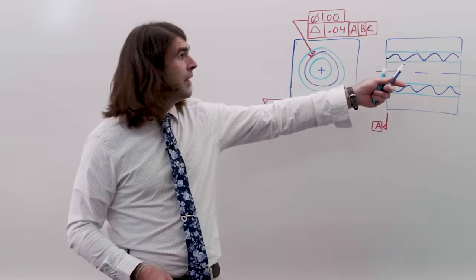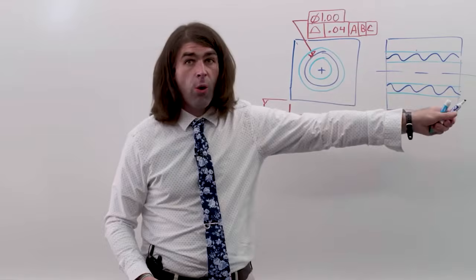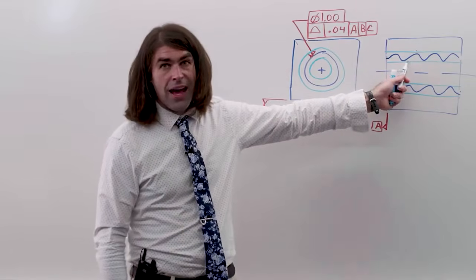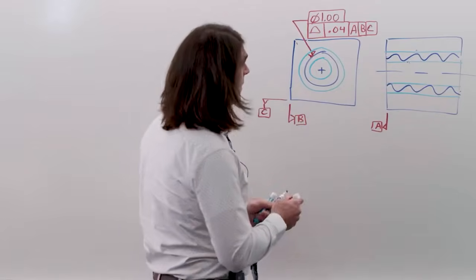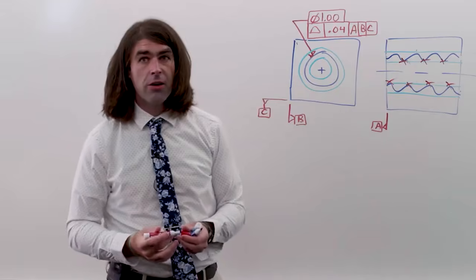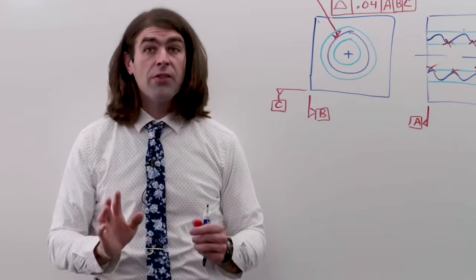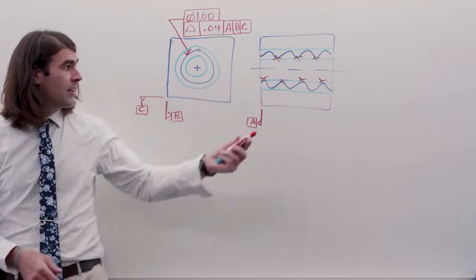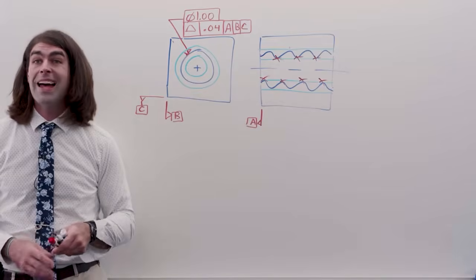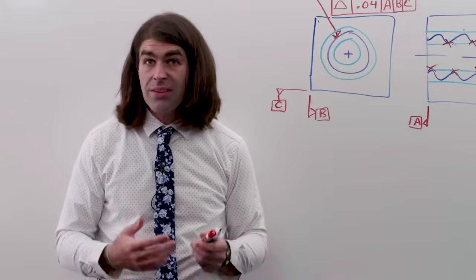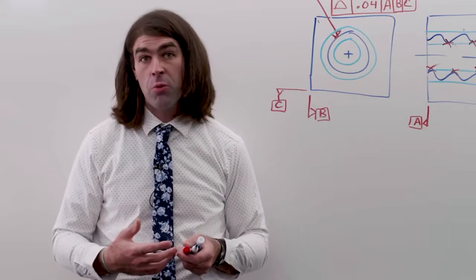Nothing is going to mate to these low points. If you put a pin or a bolt or a screw through this hole, it's really only going to touch the high points here. And when I say high points in a hole, I mean these points here, right? What would make it the smallest hole, okay? Position is only going to worry about these points. The lower points are controlled by the limits of size. So they still have to be checked, but you're just not checking them in the same way you would for a profile.